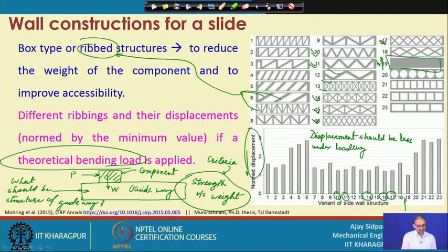So, you can select any of these particular structures depending on the availability of the machine tool or the processes which can fabricate this type of structure, because if you go with this, mostly you create this 2 bar and then you weld it, that is one of the options. Then another way you can do casting also, by which you can make this type of structures. So, by this way actually you have to find out which one is the optimum design for a strength to weight ratio, so that you can get the required result without any sacrifice.